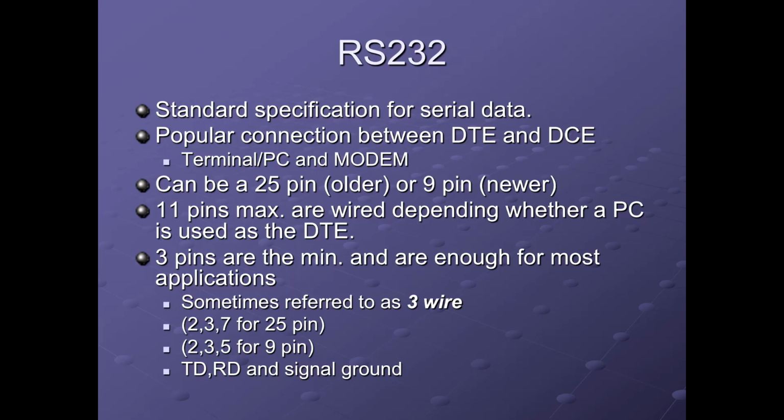So we had all these carrier detect, request to send, terminal ready signals. These were additional signals connected between the two devices, the terminal and the modem, or the terminal and the DCE, that were called handshaking or traffic signals. You could think of them as directing the data traffic between the two. Nowadays, with smart devices and buffers that are capable of processing data far beyond the maximum asynchronous serial rate for RS-232, we're really down to only 3 pins or connections for these smart devices over a 9-pin connection, as opposed to a 25-pin.